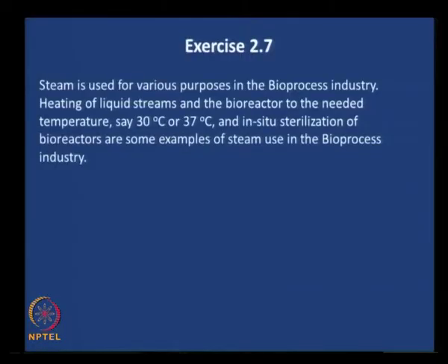There would be competition for the food that is available, which may not be desirable for the optimal production of the product, and therefore we sterilize things, we make sure that we have a clean slate when we start out with, and under sterile conditions we add the microorganism of interest into the bioreactor and then let that organism grow and produce the product of interest. For sterilization, steam is used, slightly higher pressure steam and at temperatures of about 120 degrees, 121 degrees are used.